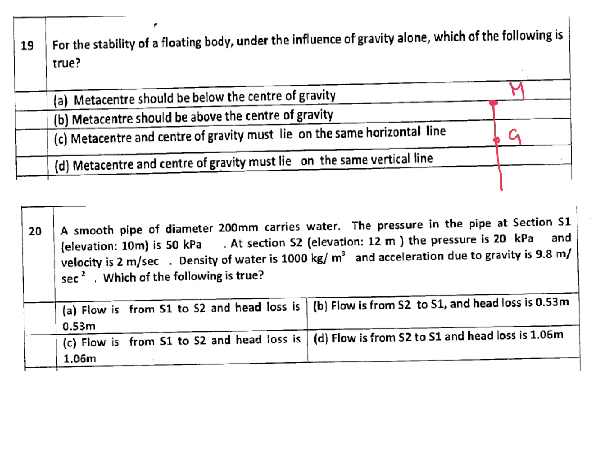Metacenter, center of gravity and center of buoyancy. So from the options, metacenter should be below the center of gravity, no. B, metacenter should be above the center of gravity for stability of a floating body. B is our answer. Metacenter and center of gravity must lie on the same horizontal line, this is for neutral equilibrium.